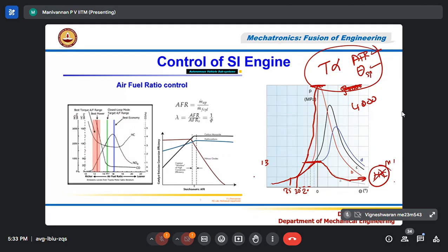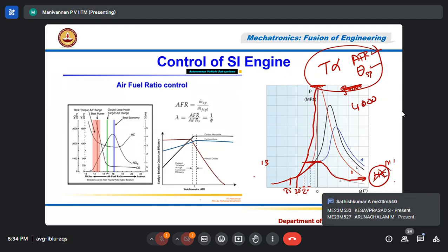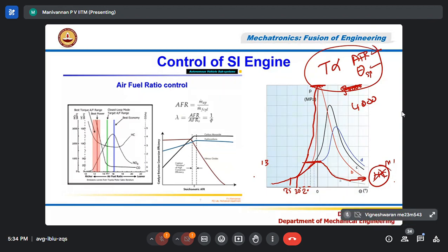Yes. So why I was asking is, is the spark timing directly linked with the cam sensor, right? Or is it the sensor that says where the piston is? The cam position sensor says whether the piston is in the compression stroke or suction stroke, or exhaust stroke, or power stroke. That's what it says. So at different RPM, the spark can happen at different timing. Yeah, you have to do it, otherwise you will not get maximum. That's what I'm explaining to you. If engine RPM increases, you have to give the spark much before.